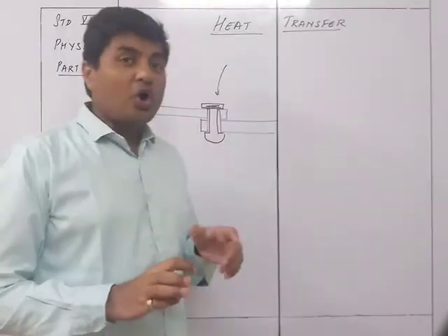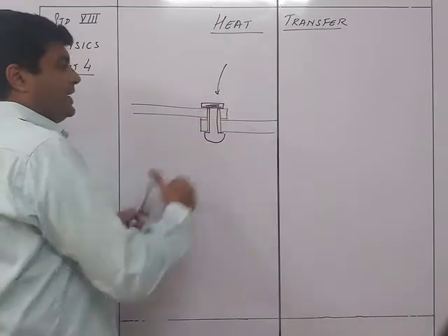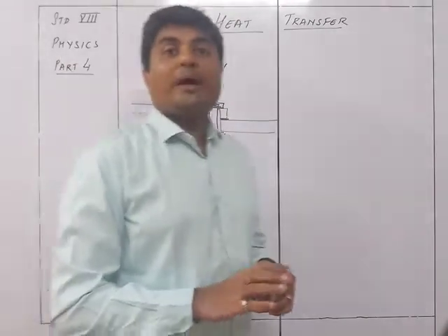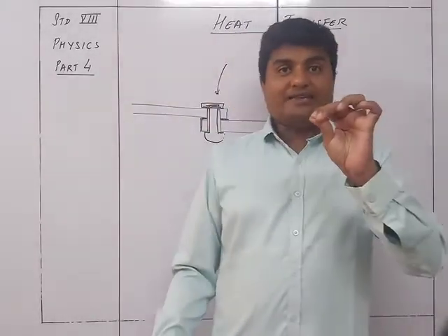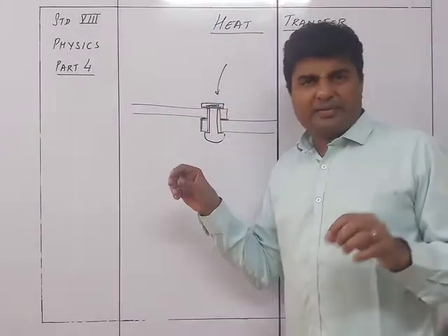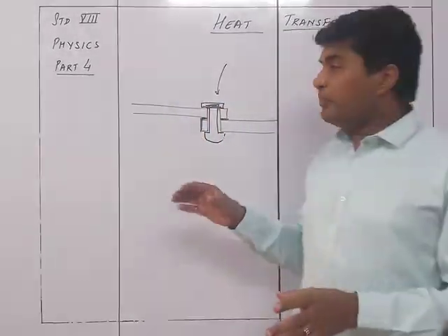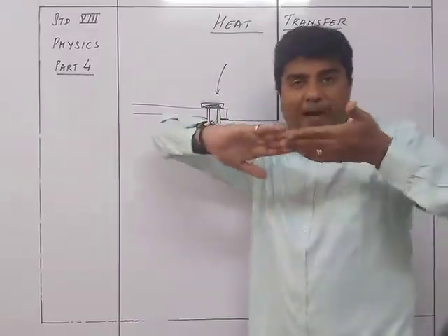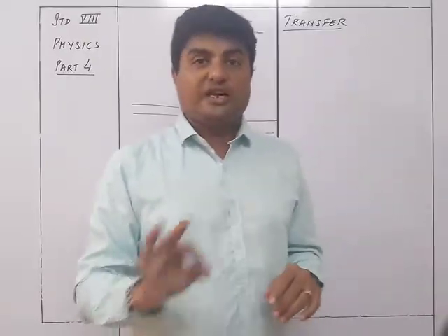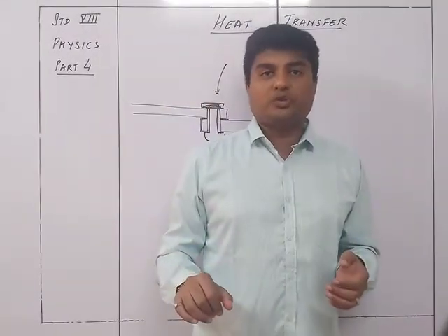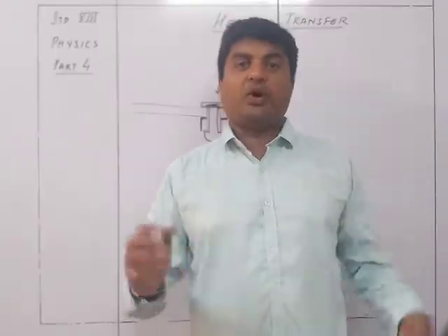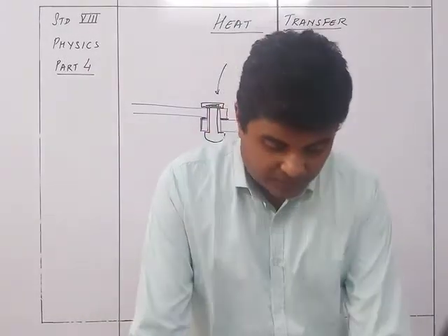Moreover, because it is hot right now, even with hammering it had already become tight. Okay, this was already filled up. But then when it cools down, it is going to contract in size. It has already expanded right now, maybe just a very minute fraction. But after we hammered it and made it tight, when it contracts, it tightens this much more so that it becomes steam proof. Then even steam cannot pass through this particular thing. That is why rivets are a very easy and fast method of connecting two plates together.